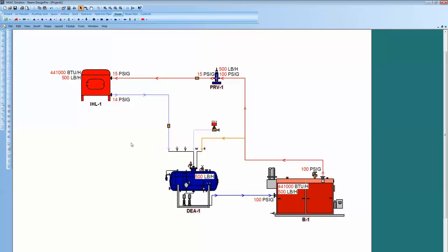The third major item is you have to have some load, some utilization, process load. This a lot of times consists of coils and heat exchangers. And then last of all, you need to have some condensate recovery method. How do I get the condensate back to the boiler? Deaerator, boiler feed pump, condensate pump, we'll work on that.